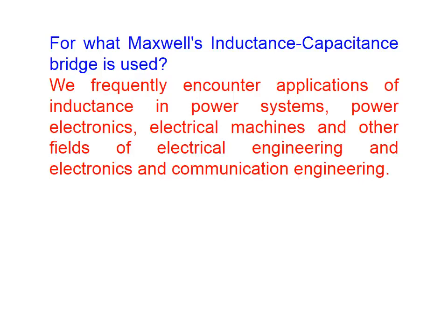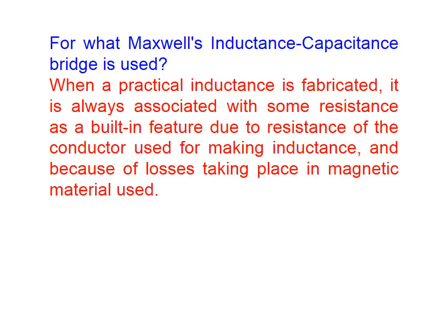We frequently encounter applications of inductance in power systems, power electronics, electrical machines, and other fields of electrical engineering and electronics and communication engineering. When a practical inductance is fabricated, it is always associated with some resistance as a built-in feature, due to resistance of the conductor used for making the inductance, and because of losses taking place in the magnetic material used in the construction of the inductance.